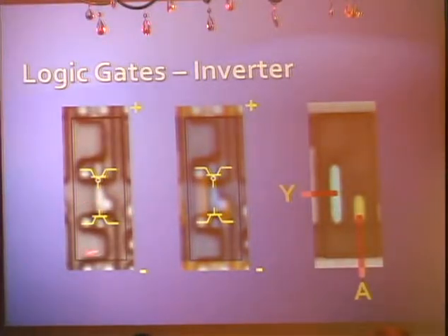Now, looking just at the bottom transistor for now, if you press the button, if you put a voltage on it, it will let current through, which means it will connect the left leg to the right leg, and the right leg is connected to ground. So if you push the button, the output will become negative. Now, the transistor on the other side acts exactly the opposite.